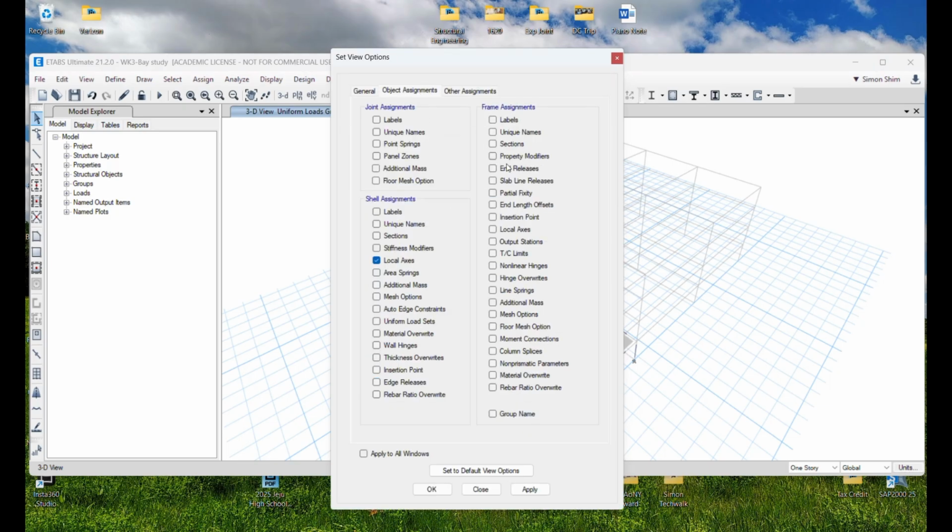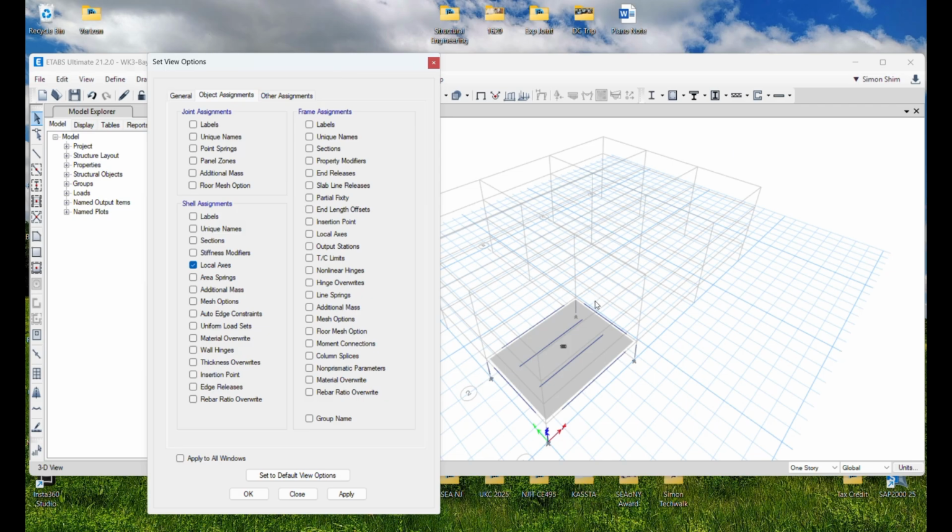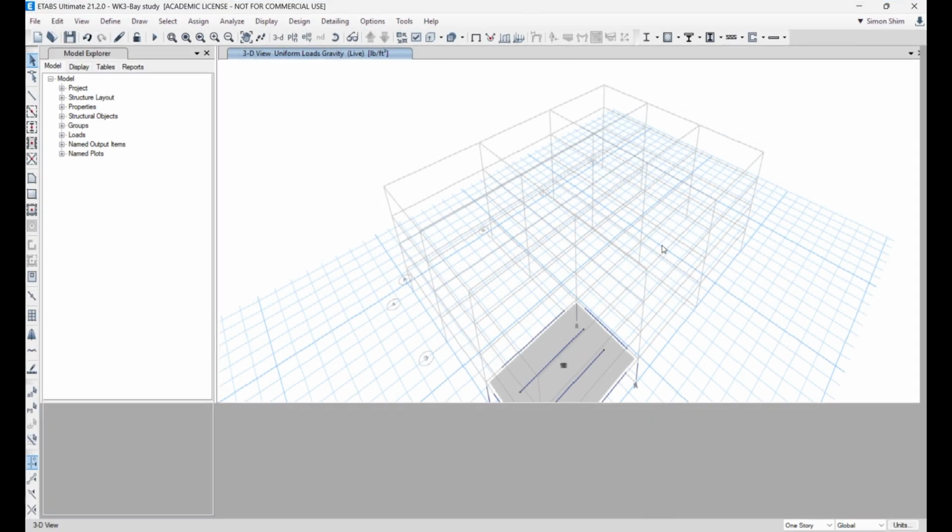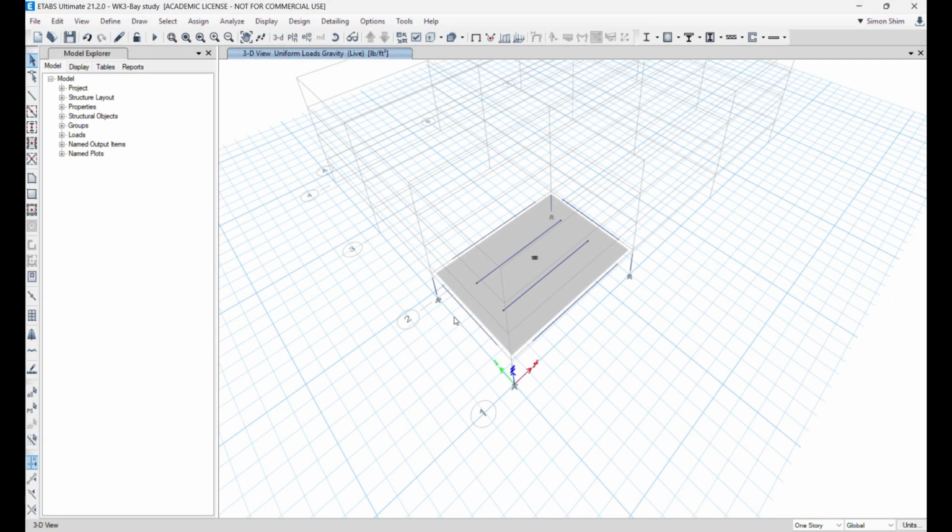pins or fixed. So here I want to make sure that each beam-to-column, beam-to-girder, and girder-to-column connection is what? Okay, here. Okay, got it. So in this example, what I did before, this column has a pin base, but they are moment connected, right? So girder to column is a moment frame, so it can develop lateral bending stiffness. But the beam to girder has a pin connection.